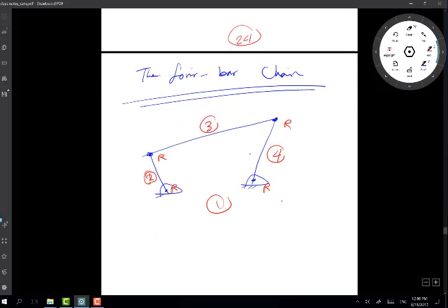Hence, it's a 4-body chain, and people have been studying this for hundreds of years in terms of whether, if you put together a 4-body chain and you select dimensions, normally my dimensions here, that will be R2, R1, R3, R4, you'll be able to realize the possibility of having at least one link doing 360 degrees, because it's not always the case. And if you want this to be the case, then you have to select the dimensions carefully, right?